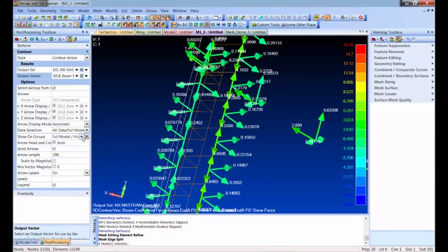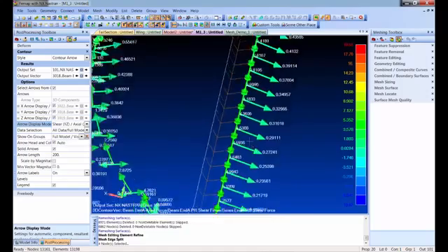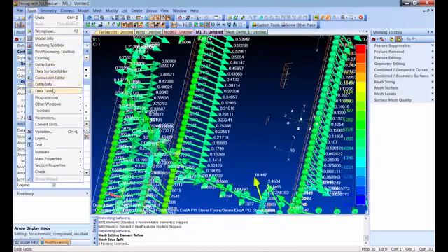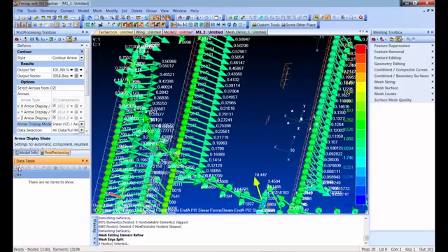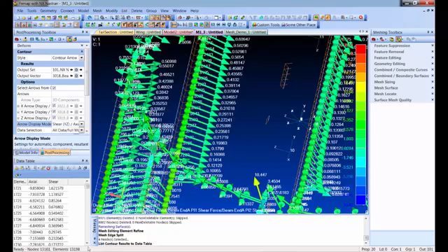Another nice thing you can do in here, I know that shear is Y and Z. I can combine those at the same time into their total shear without having to do any output calculations. And just like everything else in Femap, I'm going to turn on my data table and say list output contoured results to the data table, and now I can sort.